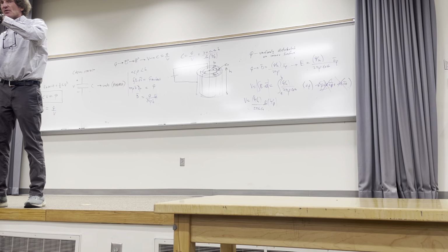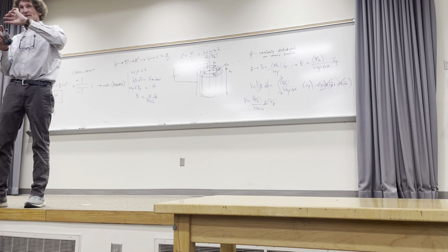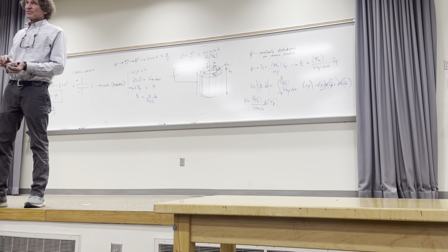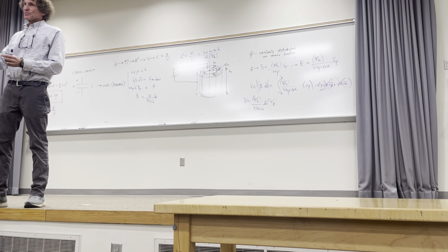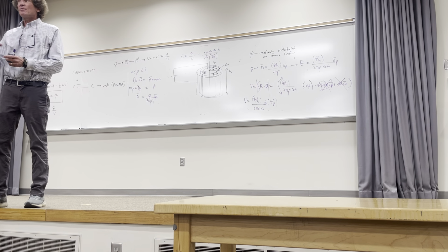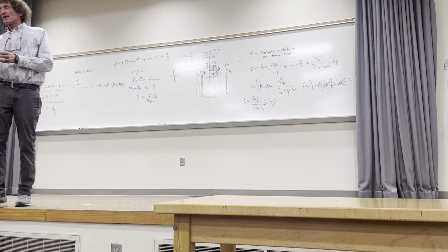It's a glow discharge that happens at the tips right before the big event, when you wish you weren't there, basically. And I remember the stuff we had to do to prevent that. We basically take all sorts of, I call it goo. If you've ever done a Bondo job on a car, you have something called potting material that's a very good insulator, and you put it anywhere there might be any kind of a frayed thing like that.